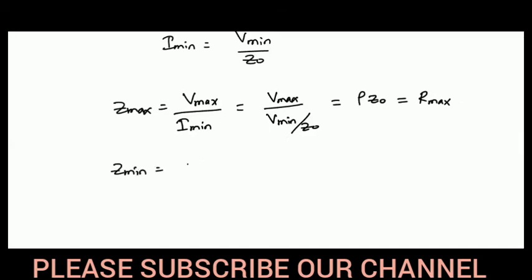Similarly, Zmin will be Z naught divided by rho. When will the impedance be minimum? When the voltage is minimum and the current is maximum. In that case, you will have minimum impedance. So these are two important relations.